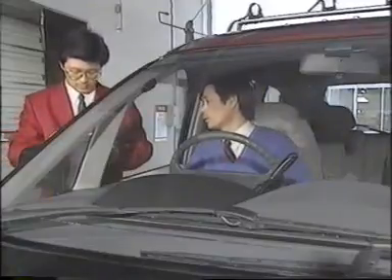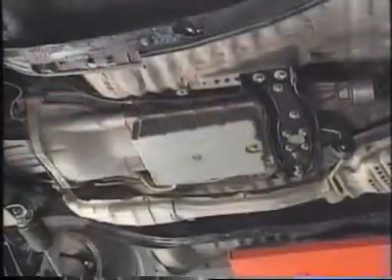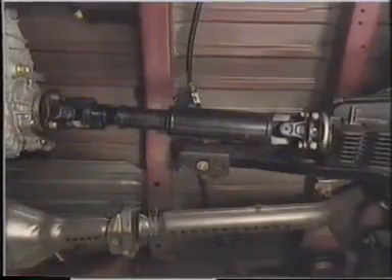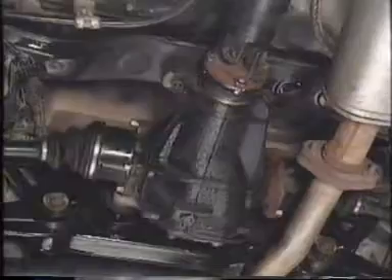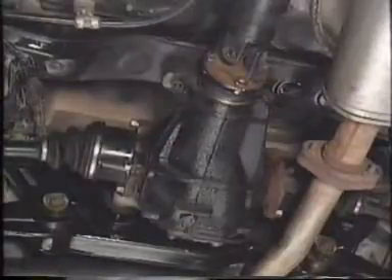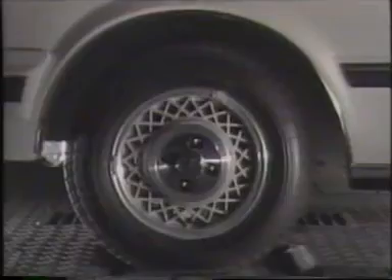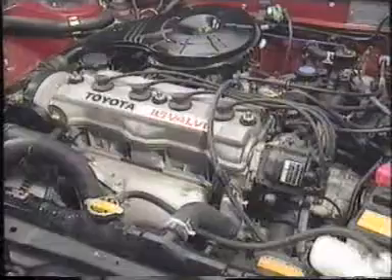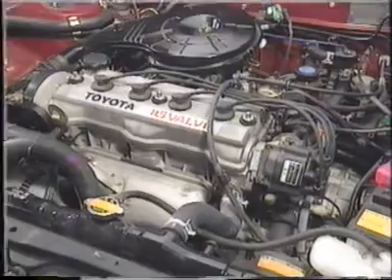More importantly, you should find out the vehicle speed and engine speed at which the problem occurs, as well as other relevant factors, and identify the characteristics of the vibration and noise as accurately as possible. When you have all the necessary information, it should not be too difficult to identify the source of the vibration.